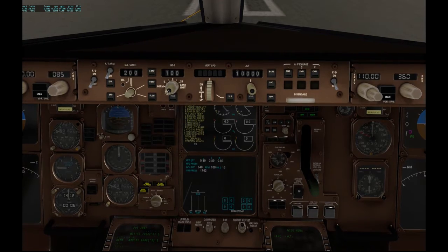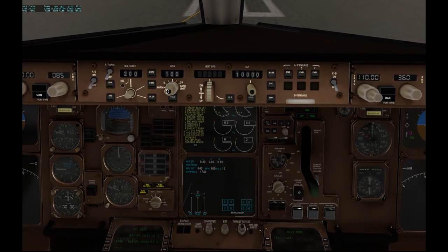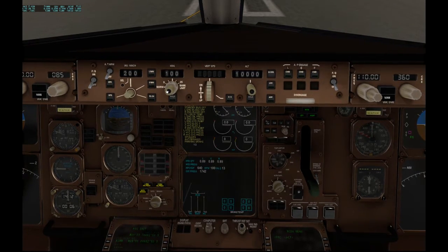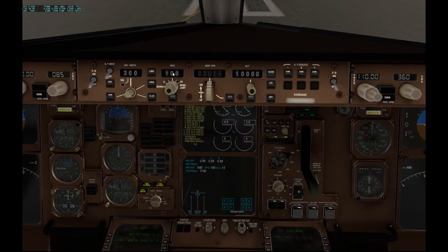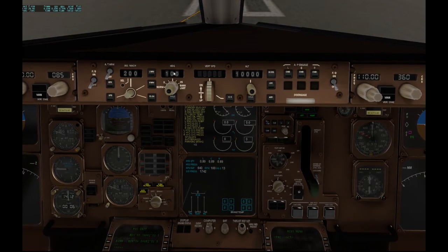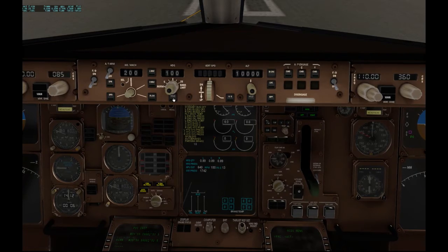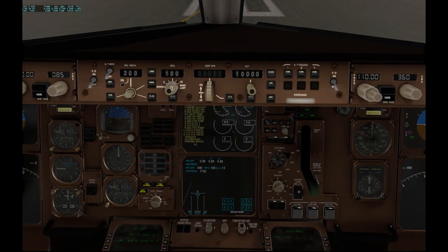And this button, once you click it, it tells the autopilot, forget about everything else. Just go where this number is. It flies the heading. Otherwise, if you click hold, wherever the aircraft is going, it's going to hold that heading. So you use this to engage the heading bug. Alright?